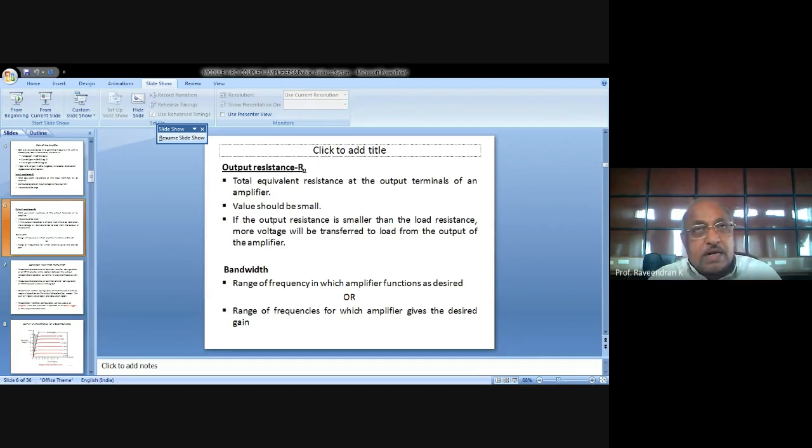So this is the reason why the output voltage has a phase shift of 180 degrees, or phase inversion, or the output voltage is in phase opposition. That is 180 degrees out of phase. Follow my point. That feature you have to note down: why the output of a common emitter configuration or common emitter amplifier is out of phase by 180 degrees. And for this reason you have to mention this equation also.